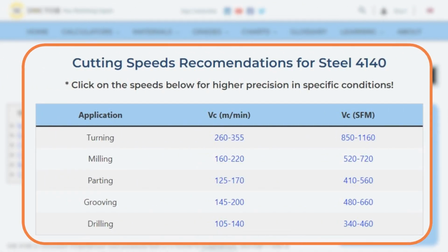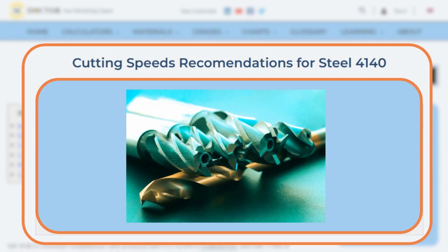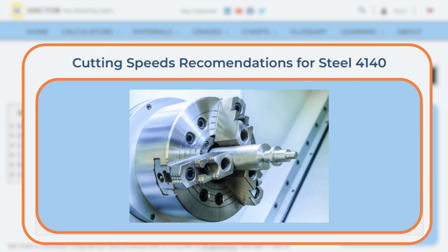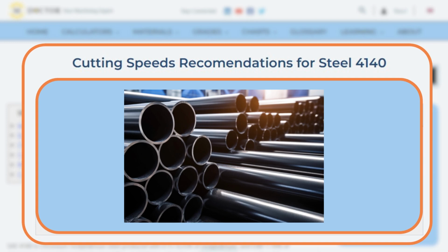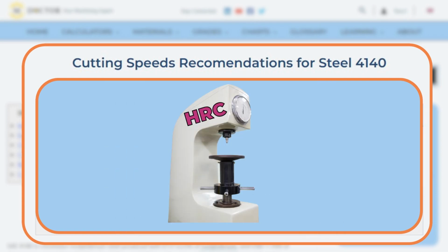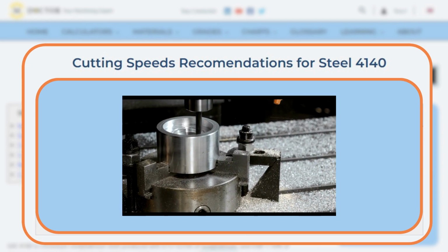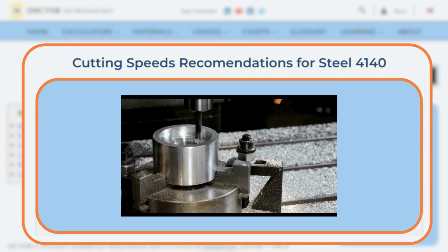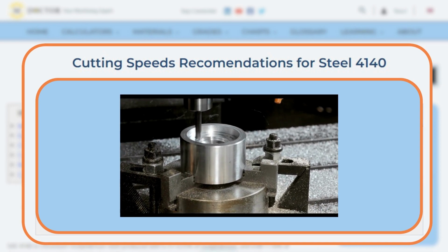The recommendation is given for an ideal situation. You are using the most suitable carbide grade. Both cutting tool and workpiece are properly clamped. You are using good quality raw material. Your tool is clamped with a short overhang. The material hardness is around its nominal value. So in most cases, the real-life recommendation would be lower, depending on your specific condition.